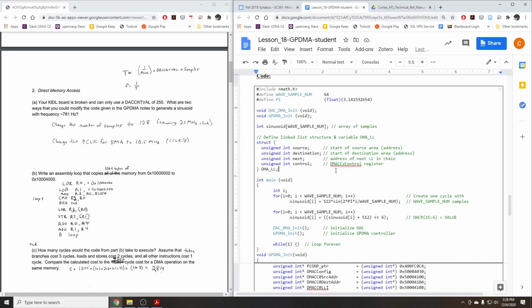Here it's important to remember that what we're basically doing is setting up a sinusoid wave in an array, but essentially we're just sampling points between 0 and 2 pi. So we're putting a single wave of that sinusoid into the DAC at a faster or slower speed in order to make it go through that sinusoid quicker or slower, and that's what lets us play a different tone: running through that wave quicker or slower changes the frequency.